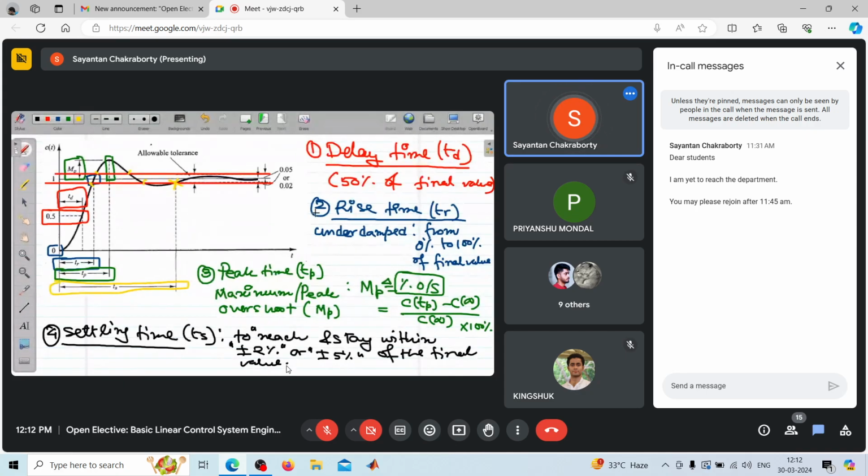Okay. Now, finally, we can also derive the steady state error. That is for steady state behavior. That I'll keep for later. Now, one note about this rise time that I want to mention is that for zeta greater than or equal to 1, that is, for the critically damped or overdamped scenario, the definition of rise time is slightly different.